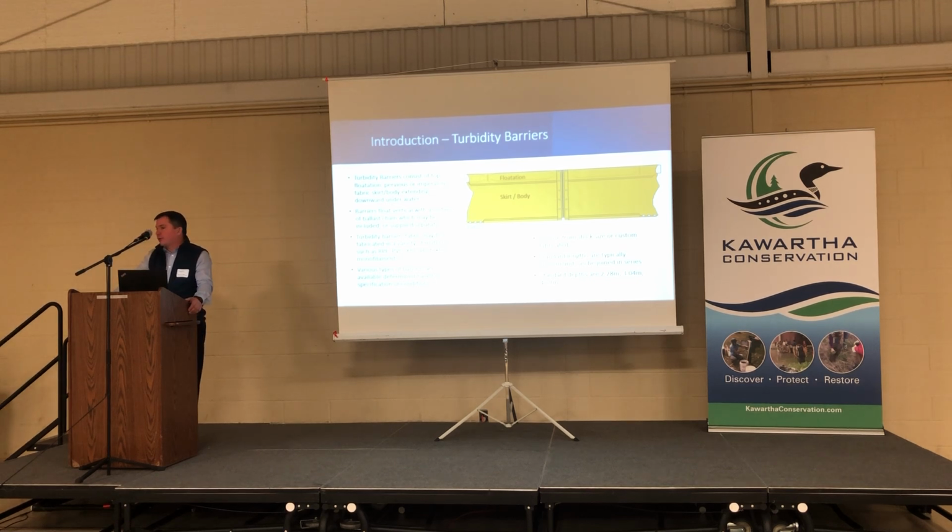Fortunately, a number of these barriers are kept in stock within about 2 hours from here. We also have a local distribution available that can provide ready access to these materials. The stock barriers have a standard length of about 15 meters long and depths of 2, 3, and 4 meters deep. So those are more or less the standard sizes. Beyond that, they will be custom in nature and certainly possible to supply.